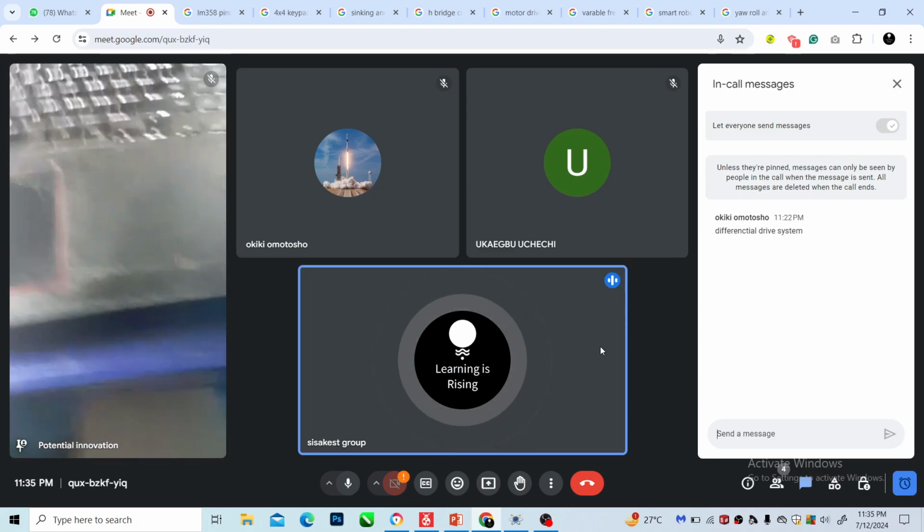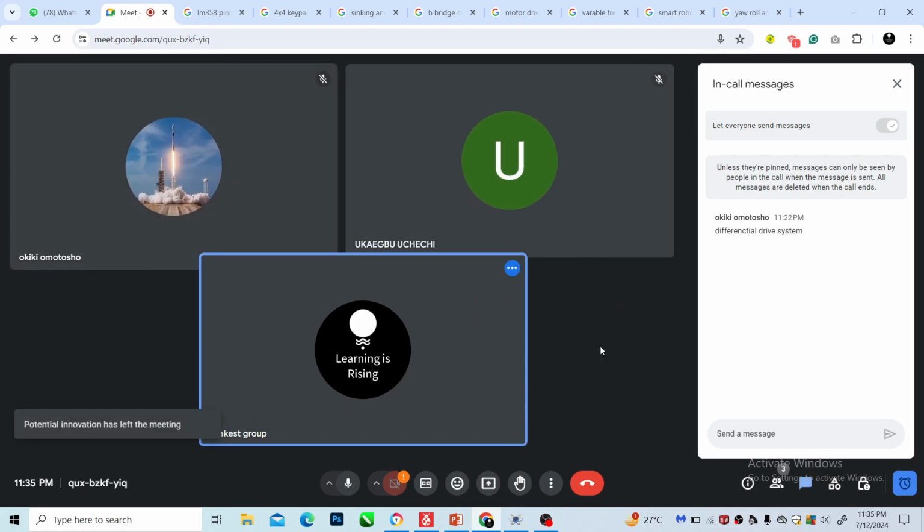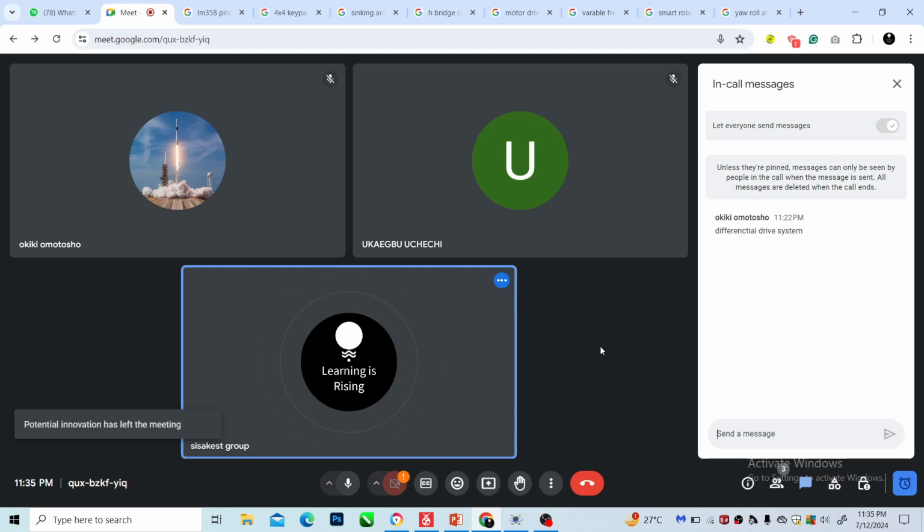You can have a motor driver even at another level. Sorry, one minute. If you are working on a bigger voltage, it's not that this kind of motor driver will not work for 24 volts. It will actually work for 24. It works between, I think, 4 volts to 36 volts, but it might not be able to support the higher current that you are looking for.